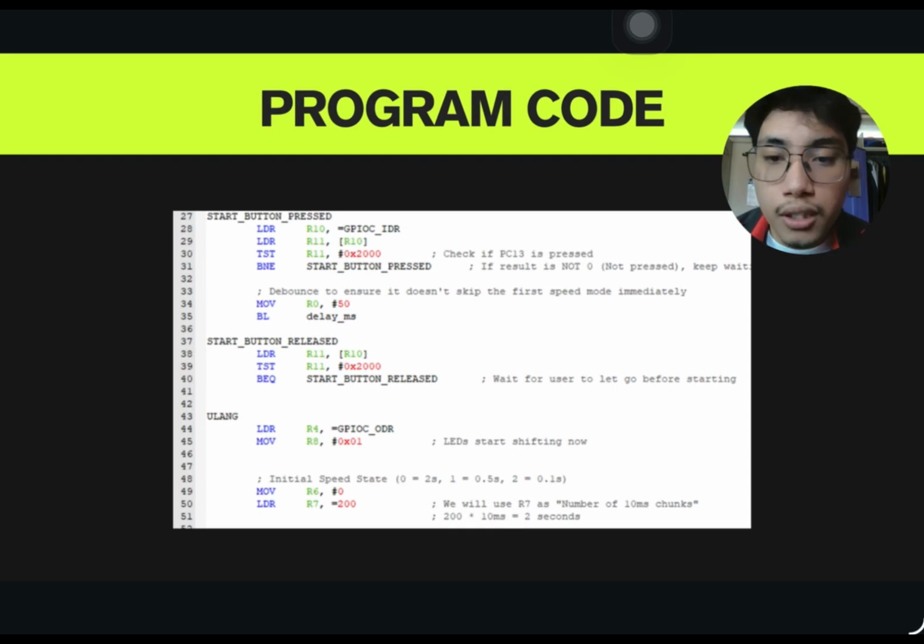So for the start button release, we load the current value of R10 into R11, and then we test again if it is equal to 0x2000, which means the button has been pressed. If the button is still pressed, it will return again to the start button release.